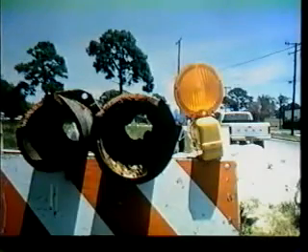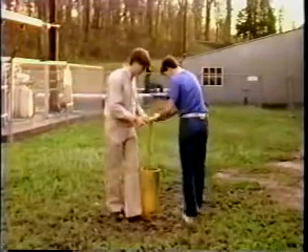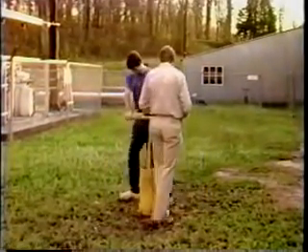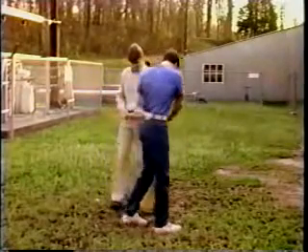One of the common problems is a great deal of tuberculation or scale inside the pipes. This tends to reduce the carrying capacity of the line. This type of problem usually shows up fairly gradually. If the loss of flow from the hydrant occurs rather abruptly in time, it's probably due to someone having left a valve closed or partially closed in the system. You need to go out there and find that valve and make sure it's completely open, because gate valves in the distribution system are supposed to be open.